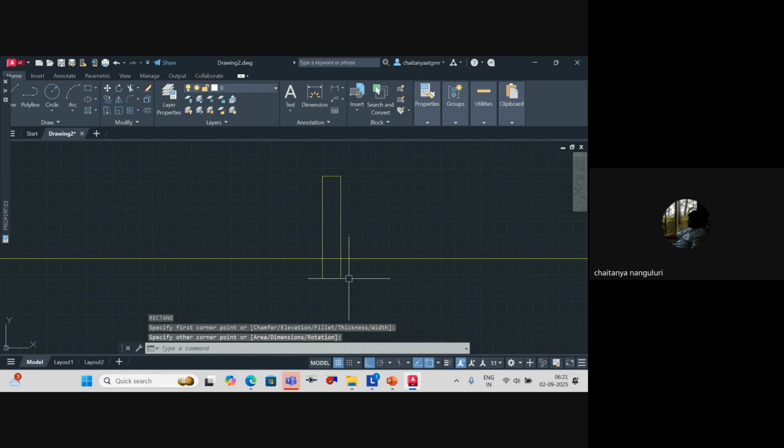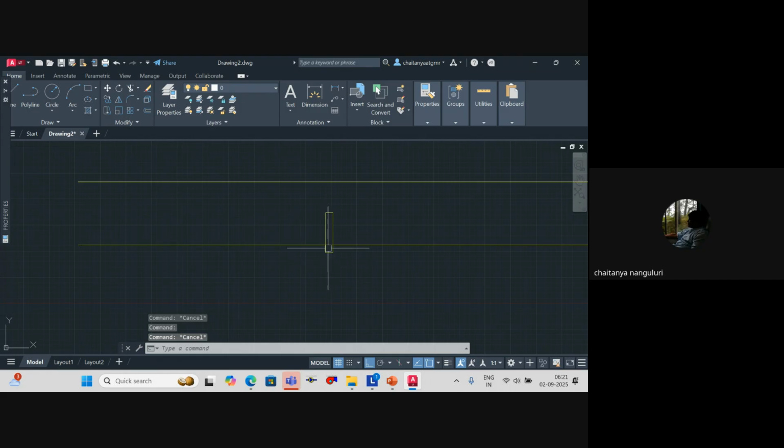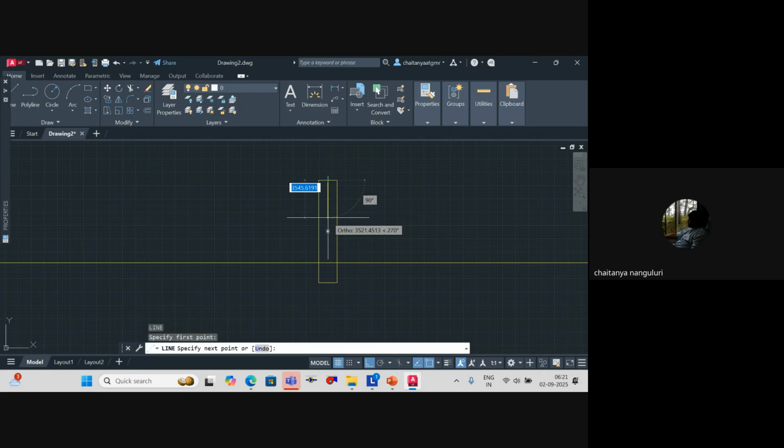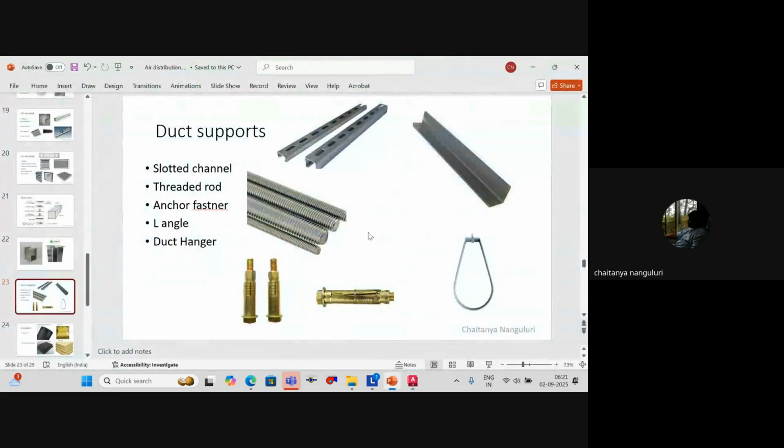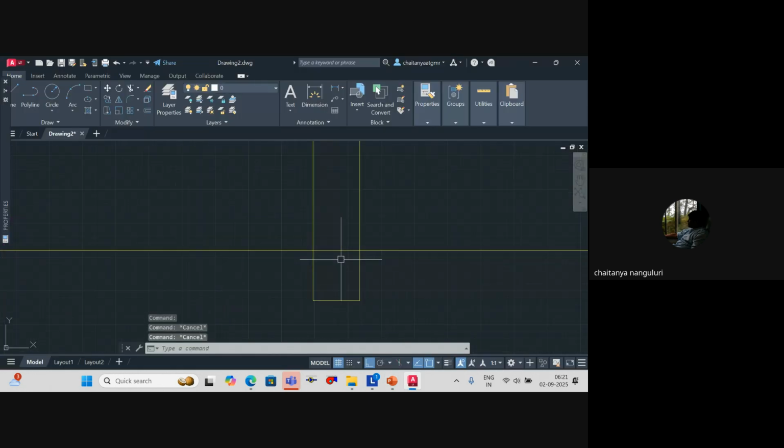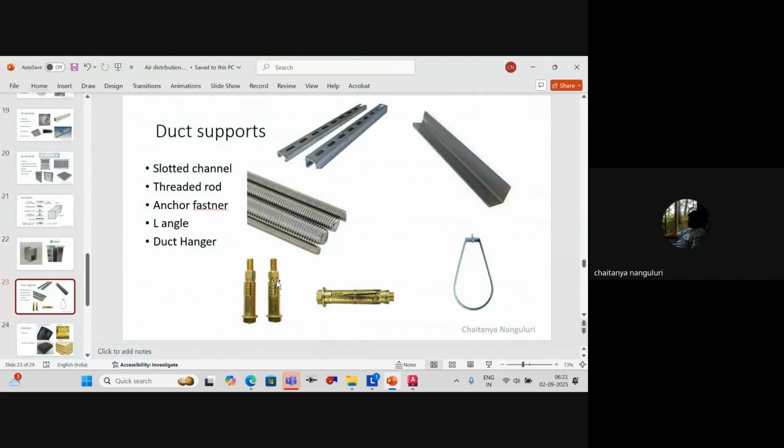First, you take this particular rivet, drill the slab, and insert it into this. Once you insert it, at this location you basically have a threaded rod. So this particular thing will be a threaded rod. Once you have this threaded rod, anchoring is what we do. When you anchor it and rotate it, you're forcing this wedged joint to enter into this gap.